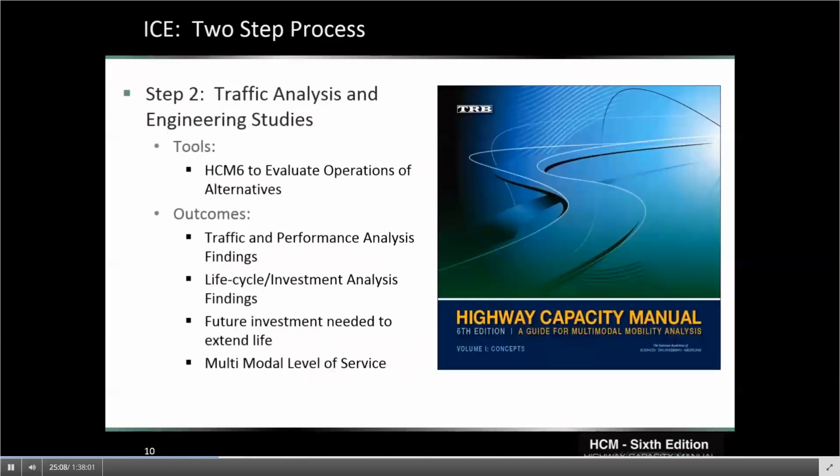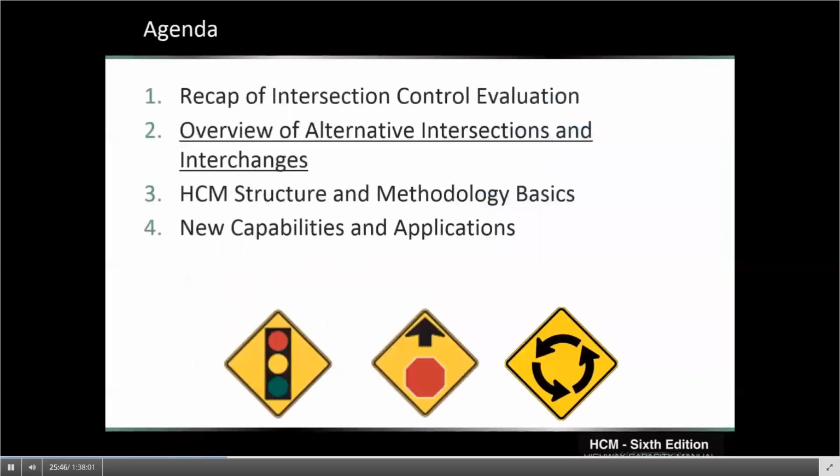So we can predict traffic performance, we can get delay, level of service, and travel times, and we can get multimodal performance measures, both in isolation as well as integrated into, for example, a life cycle cost assessment framework. That doesn't mean that there is no space for microsimulation in ICE. In fact, several state ICE policies have a third step that looks at a microsimulation approach. That's certainly feasible, but the idea is that something is needed in between a planning level tool like CapEx and a very operational simulation-based analysis to help contrast and compare some of these alternatives.